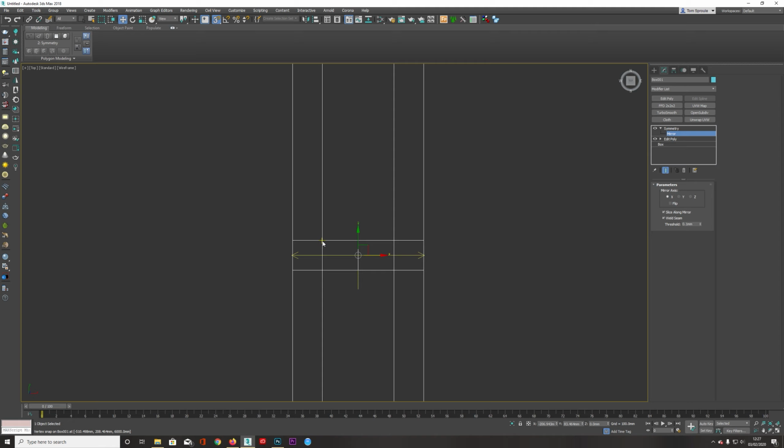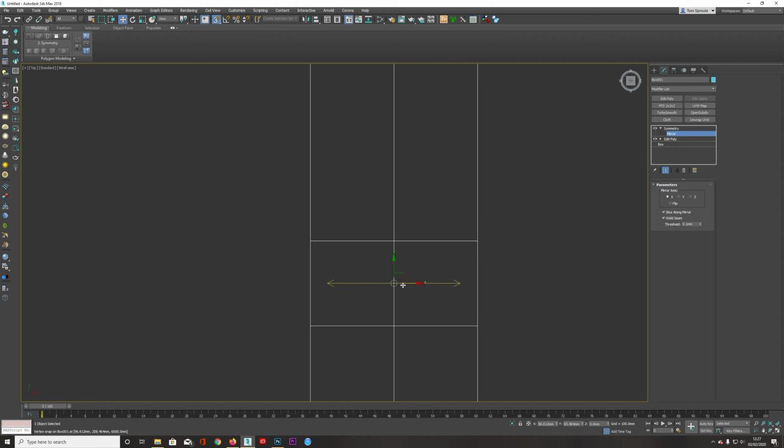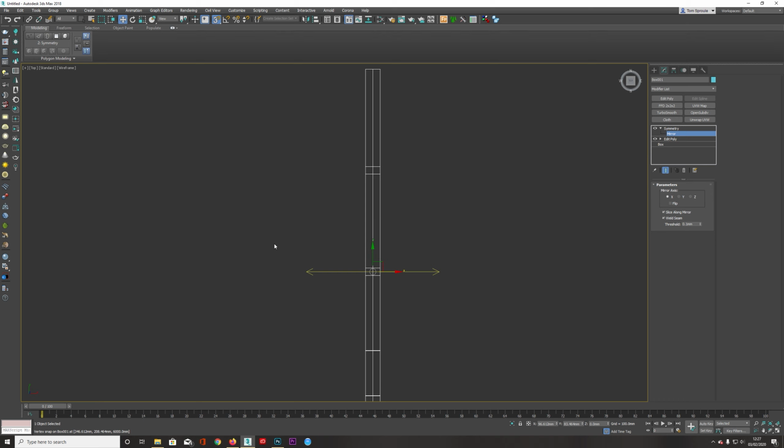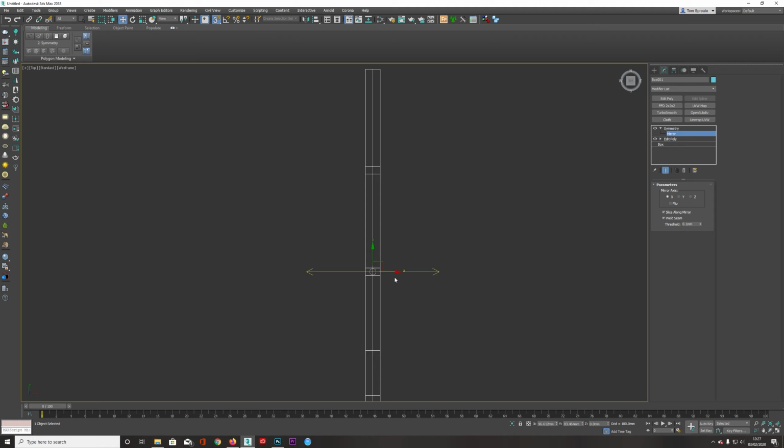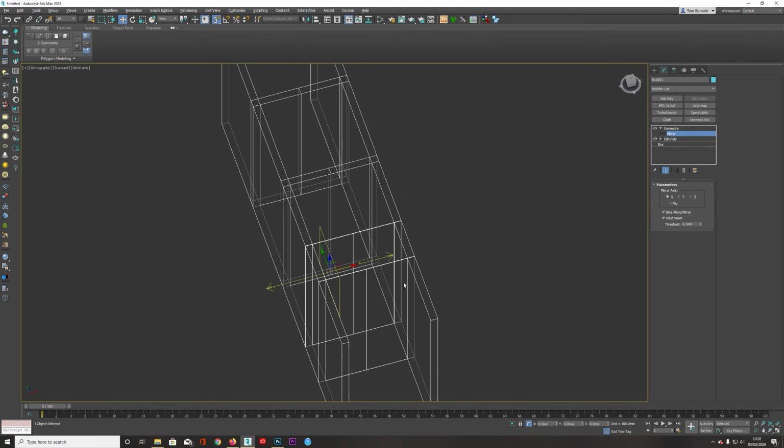And then I can just take this edge. I can just snap it here, right? So basically I can take this mirror where it is, snap it here, and then I can decide exactly where I want this mirror. So earlier on I said 2 meters 90 across, so I want half of that. That's 1,450. So if I take this and I move it, this is an x-axis here. If I move it by 1,450, I need to press this first, and this says, okay, this point here is 0. So now I'm going to go minus 1,450, and we've got that out there.